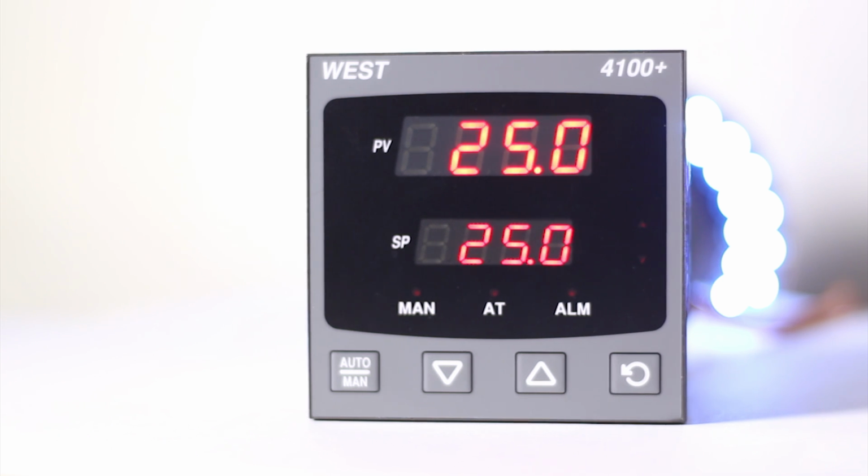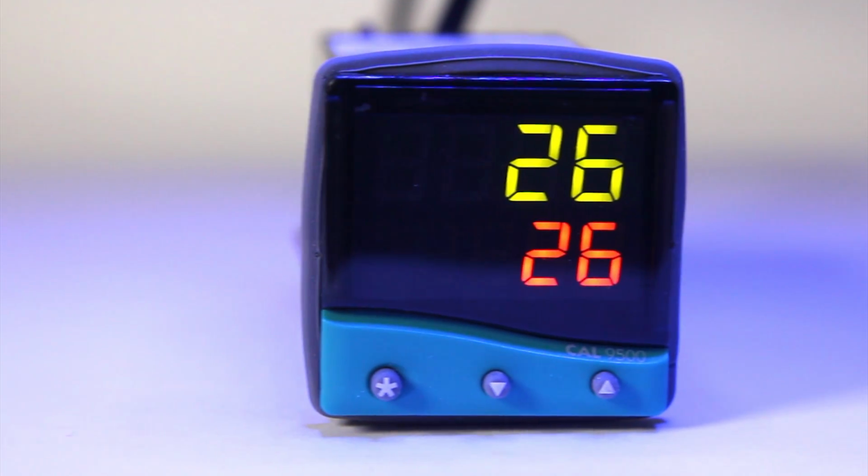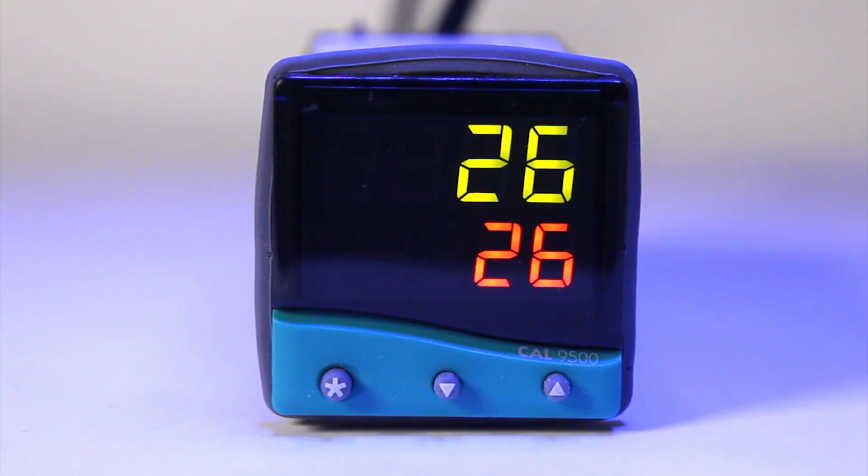The use of hysteresis is normally associated with the use of an alarm as a signaller rather than a pure warning. For example, if you wanted a damper to open as the process reached a certain temperature, you would probably not want it to close again just because the temperature dropped 0.1 of a degree lower than the alarm point. This is where hysteresis is useful. It must be remembered that even on products that do not have an adjustable alarm hysteresis, the minimum amount of hysteresis must always be applied to the alarm, and this is usually set at one least significant display digit, so normally 1 degree or 0.1 of a degree.